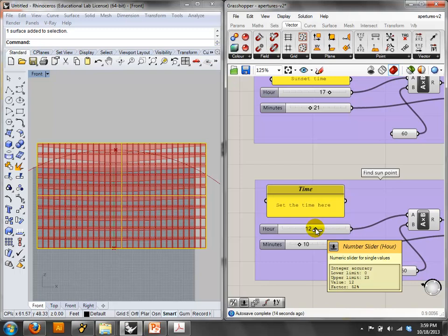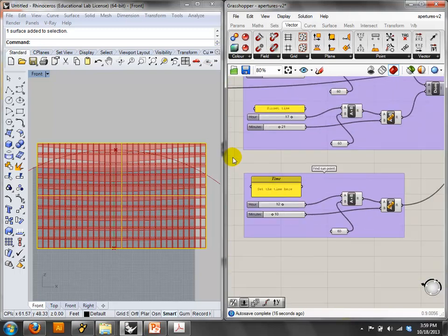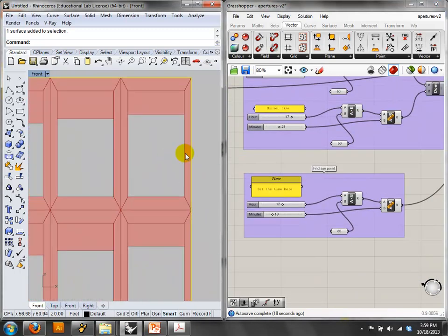And the way that this script works is that, first of all, and this is really handy, I take the lofted surface and I scale it down a little bit, and then I loft those two together, and it gives me the frame. Then what I did was I extracted that line from the inner frame, and then I moved it by some amount depending upon the angle of the sun, and I loft those two together. That's it. So it's pretty straightforward.